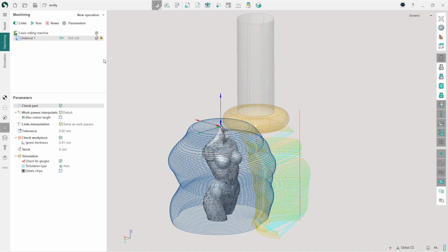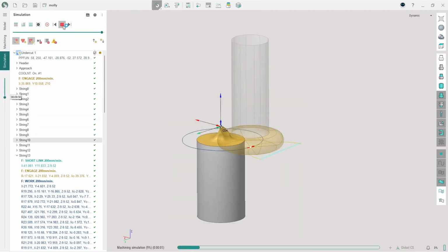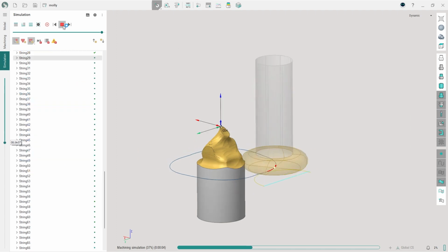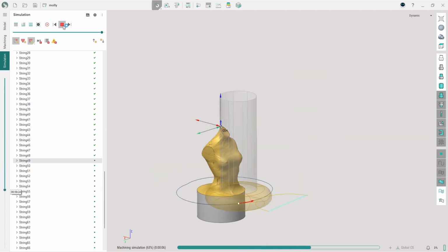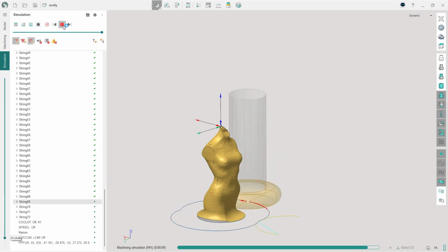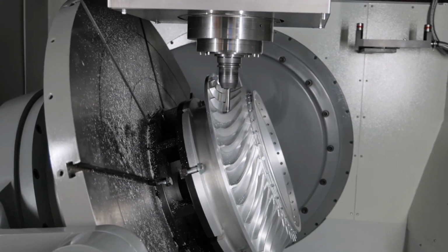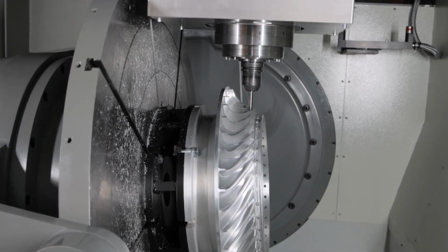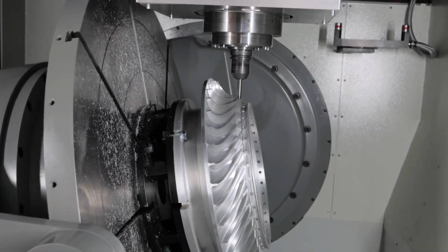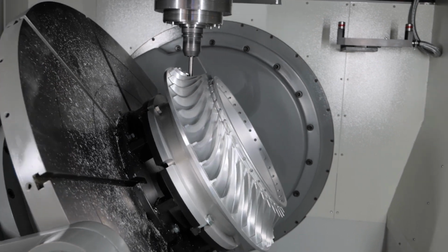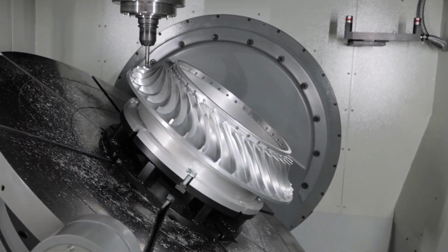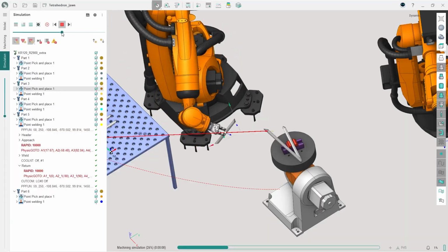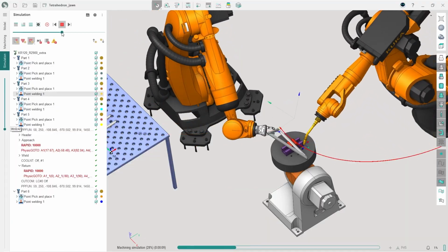The second improvement is the strategy for 3-axis machining of undercuts. Now you can easily use tools like Lollipop, Disc Tool, and Slot Tool to reach areas where it's impossible to remove material using end mills. Working on multi-axis machines has become safer, thanks to intelligent control of tool approaches and retracts using TCPM mode and a local coordinate system. With the updated pick and place function in SprutCAM X Robot, users have precise control over the trajectory using node points.